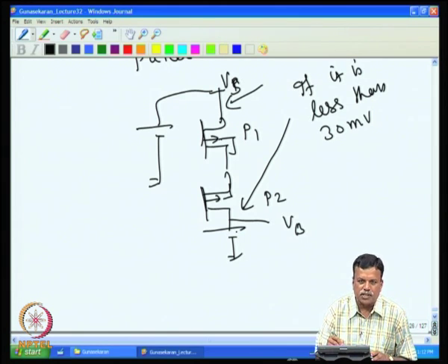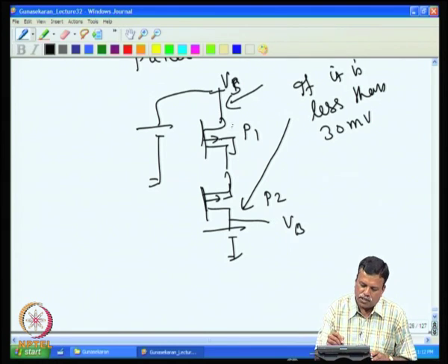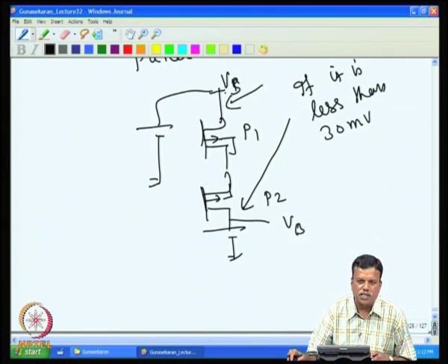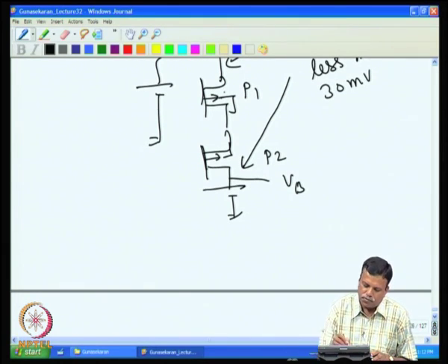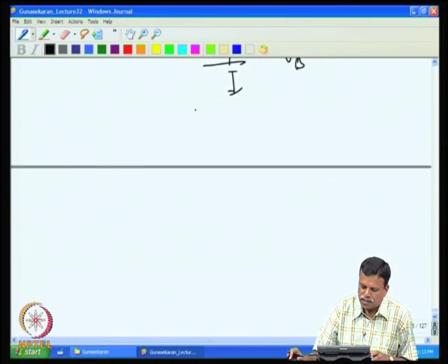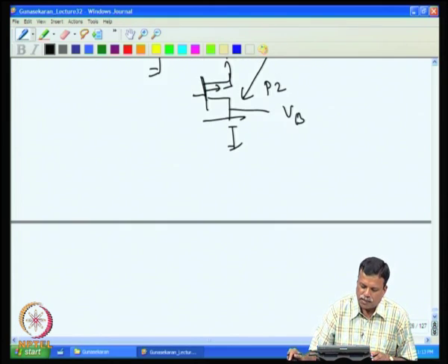If the solar cell voltage is more than the battery voltage, only then you switch on. So, to detect accurately, P1 and P2 are switched off, then the solar voltage and the battery voltage are measured, and then the decision is made to switch on the battery.